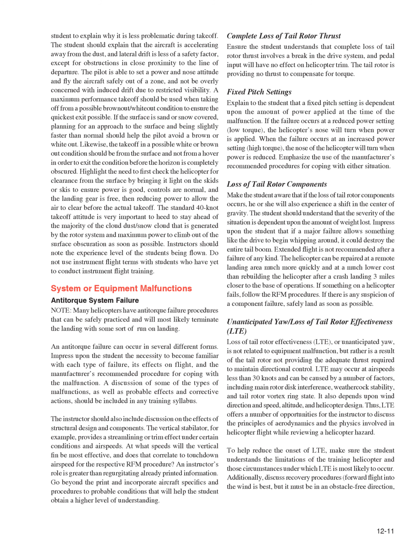Extended flight is not recommended after a failure of any kind. The helicopter can be repaired at a remote landing area much more quickly and at a much lower cost than rebuilding the helicopter after a crash landing 3 miles closer to the base of operations. If something on a helicopter fails, follow the RFM procedures. If there is any suspicion of a component failure, safely land as soon as possible.